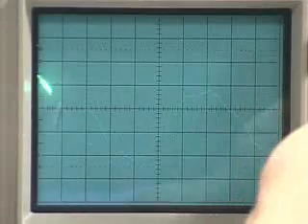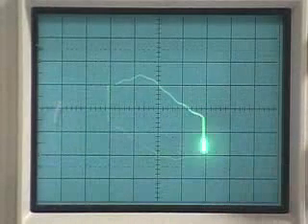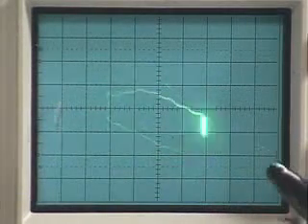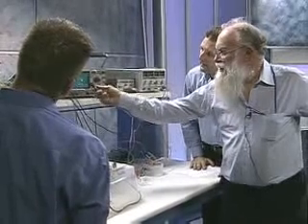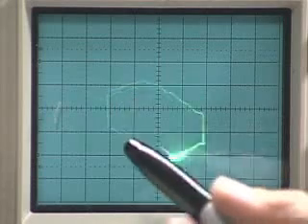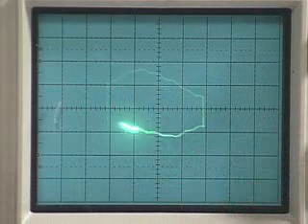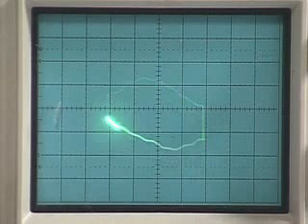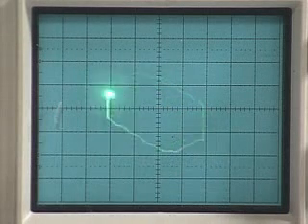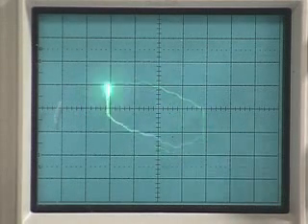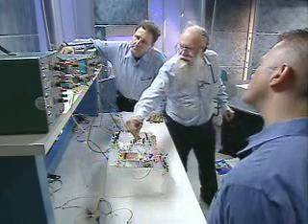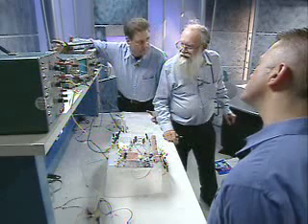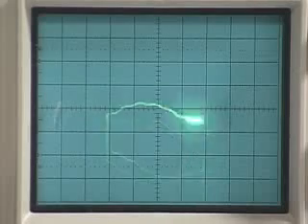This is an XY plot. You're just looking at what we're pumping into that bridge. Now, when we put this into XY, we have a signal that's wobbling around a little bit, but it is well behaved. If this was sloping left and right, we'd have a lousy balance of offset. If we were sloping this way, we'd have terrible errors. It jumps all the way because it's so sensitive. It's measuring the temperature, we're talking about just 1 part per million resolution.